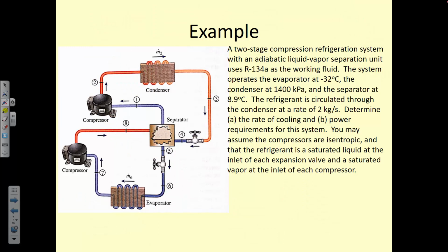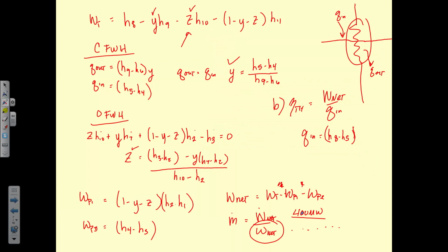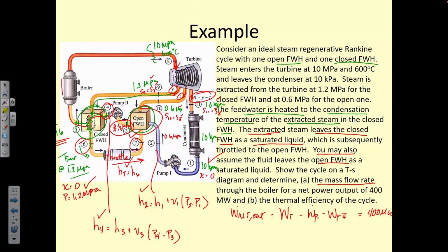Yes. The T saturation at state 6, do you have the value? No, I didn't do any values in the problems. Is the value the same as in the pressure table? I'm just curious. What do you mean? The temperature you get is the same one that we were talking about earlier. Oh yeah, it will be, because it's telling you what the saturation temperature is at 1.2 megapascals. And that's what we use for that value, for T5 T-sat. T6 and T5 are the same temperature, and that's the value you use.